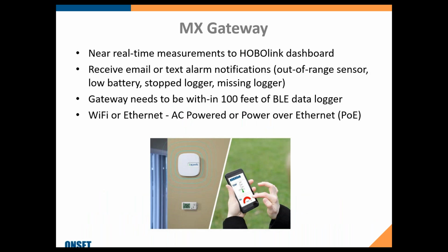So I touched on the MX gateway. Really what this is going to do is, like I said, the more hands-off approach. So it's going to take the measurements from the MX loggers, those Bluetooth loggers, through that Bluetooth signal, and send it to our HoboLink cloud server. And the way this works is it will connect to Wi-Fi or Ethernet. It does need to be AC powered, but you can plug it into PoE, so power over Ethernet.